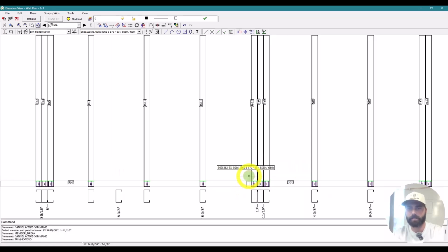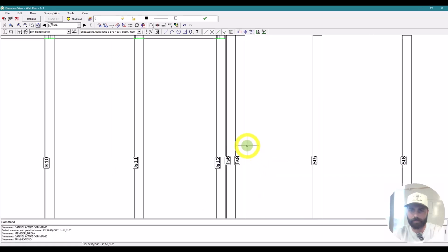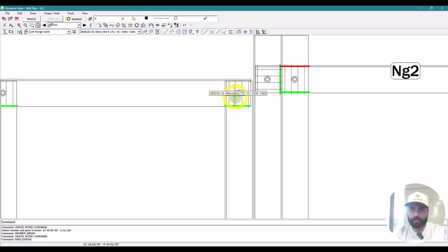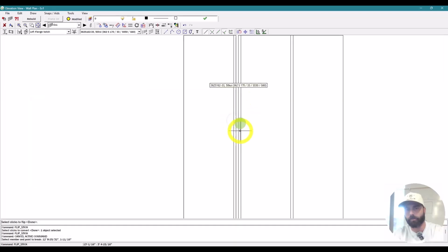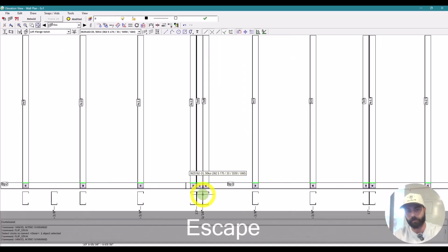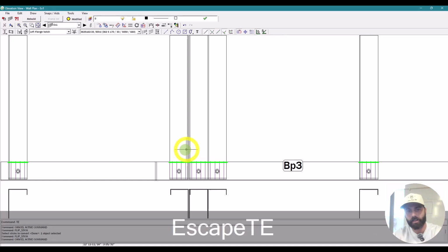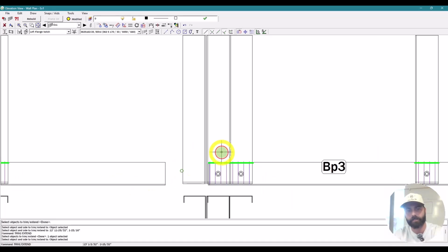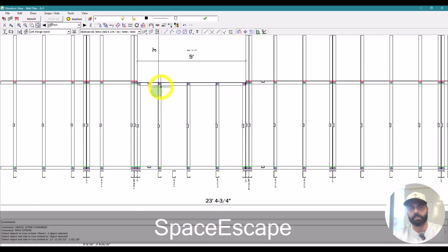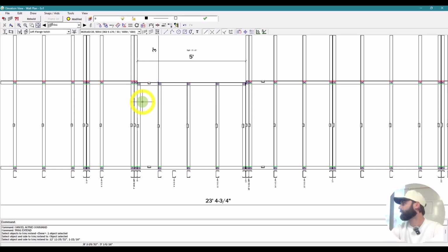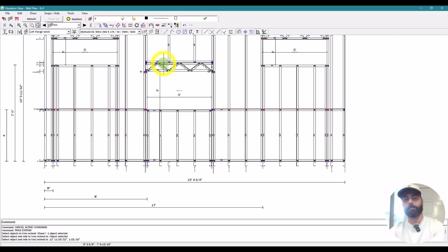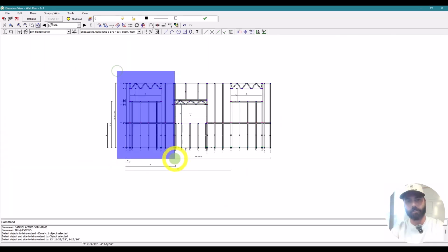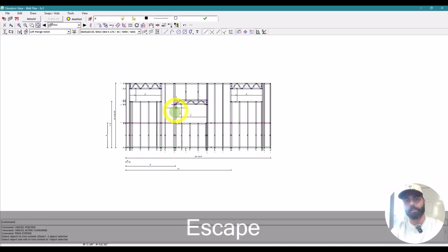And now this sill can ship independently. This header can ship independently, and the panel is now here, an individual header. So this is where uploading the elevations and showing people, oh, this is a header floating up in space. If we're shipping 60, 80 panels on a 2,000 square foot house, it helps to break these into more manageable pieces, especially if you're working on multiple level structures.